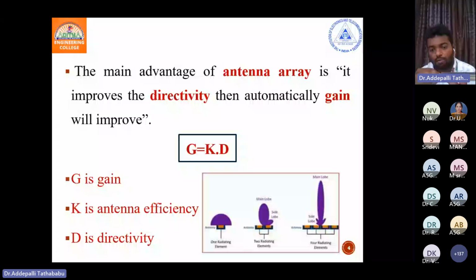That is called input power or applied power. Some signal, due to mismatch between the source and feed point, is reflected back. So that is called reflected power. The remaining power is accepted by the antenna, that is the accepted power. Then the antenna sends it into the free space.